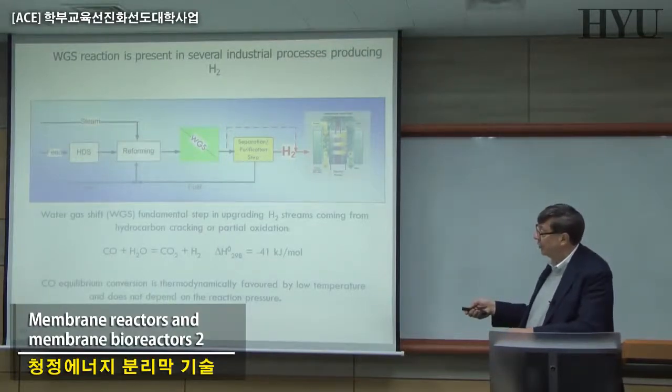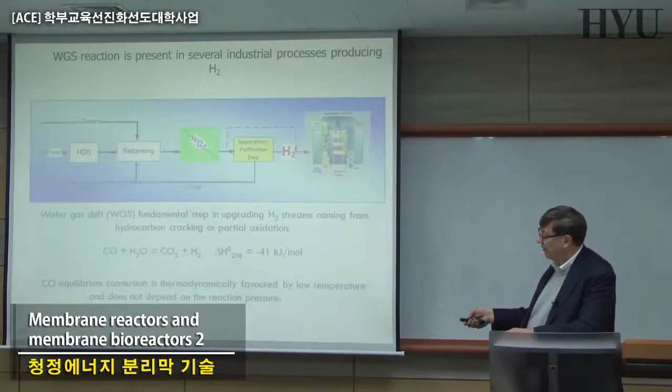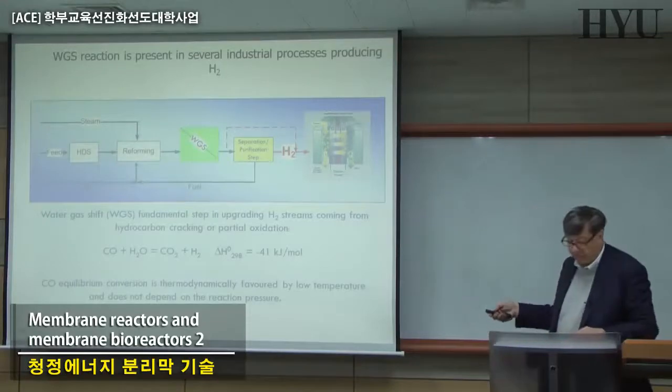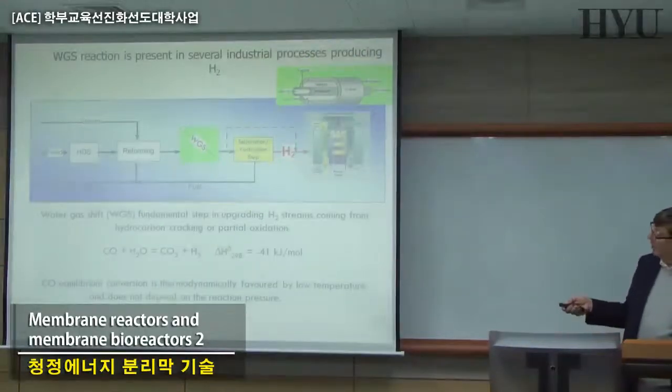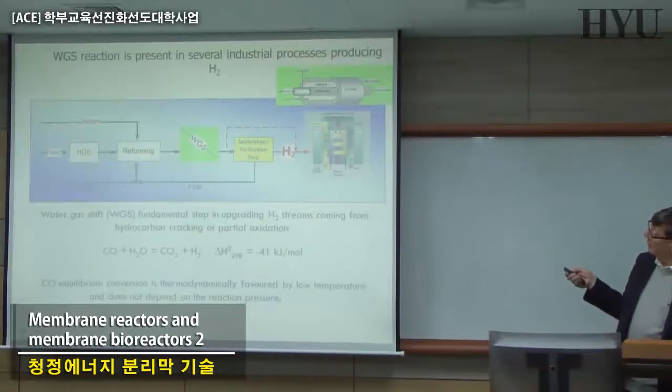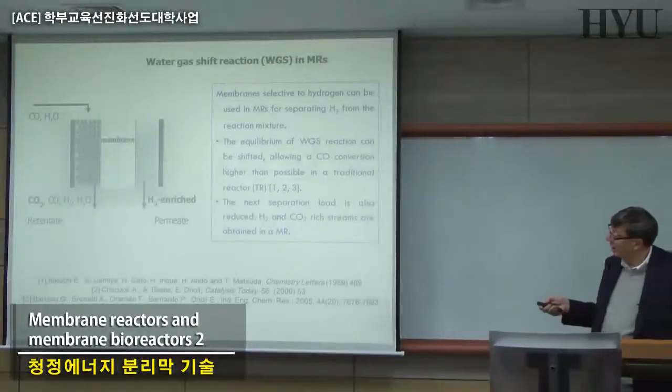So the water gas shift, as you can see here, is a fundamental step in upgrading the quality of your hydrogen, and that is the reaction we are considering. That is a reaction that is thermodynamically favored by low temperature, and in principle, as we mentioned before, does not depend on reaction pressure. However, if you are working with the membrane system, we learned that the pressure can also have a positive effect here.